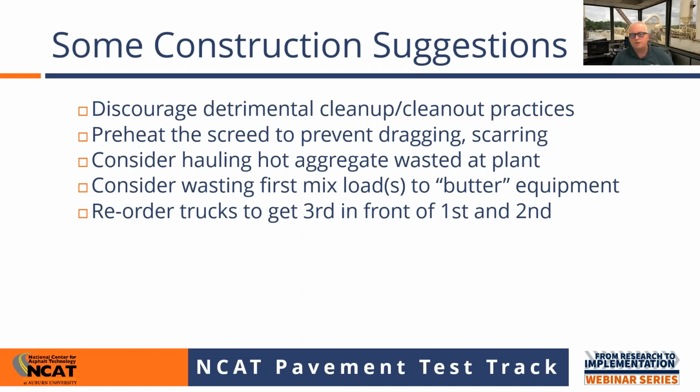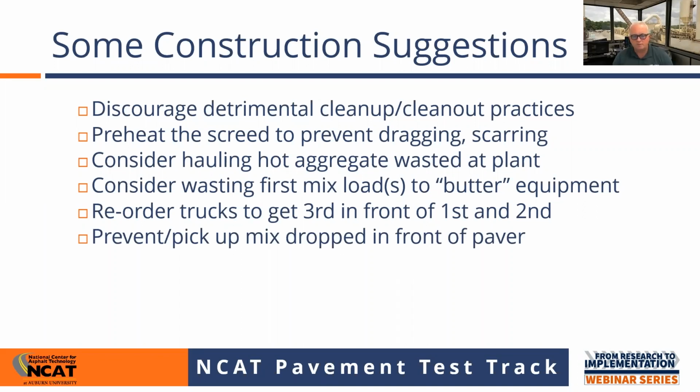If you want to consider that previous suggestion and say, well, maybe we should waste our first load and run it through everything, then you've got to have a specification framework in place to support that. The contractor either needs to bid the job knowing that they're going to have more waste than they typically have, or you've got to be willing to ticket that load and pay for that load and compensate them for it. And that's what I would advocate doing. Just have it set up in the specifications that there's going to be so many tons at the beginning of the run that you're not going to put on the road. And you might even combine those last two suggestions and still pay for a wasted load.